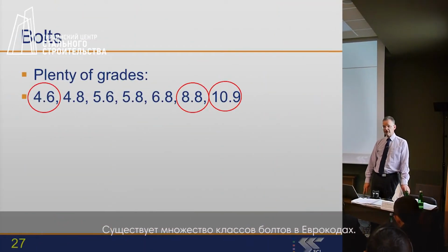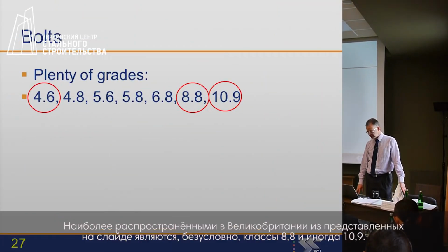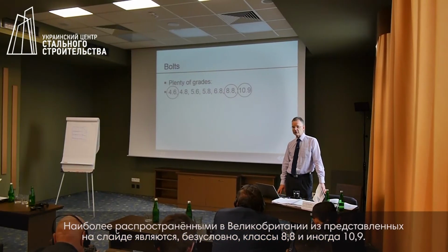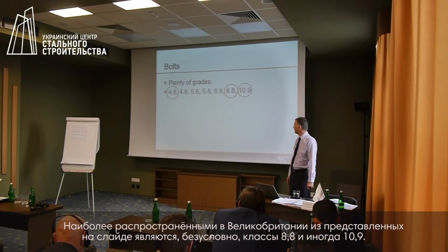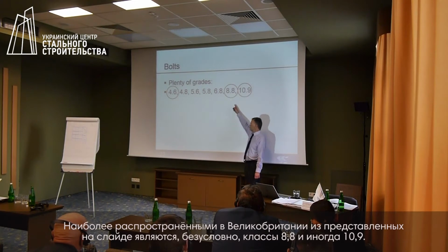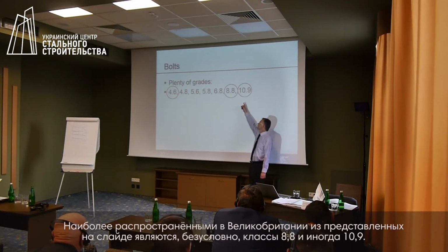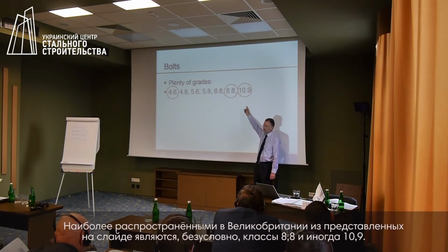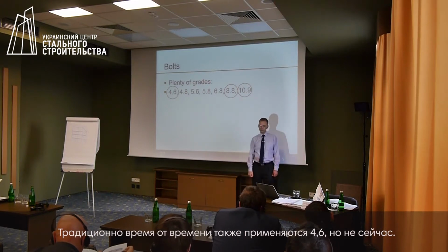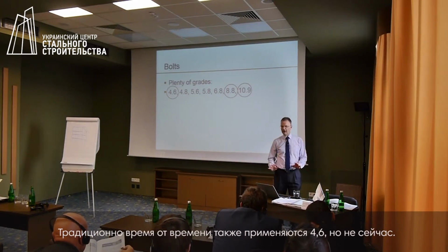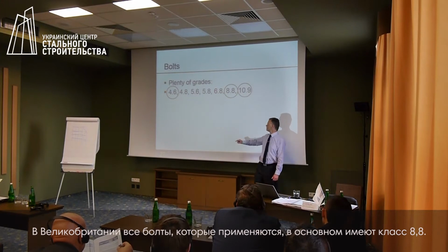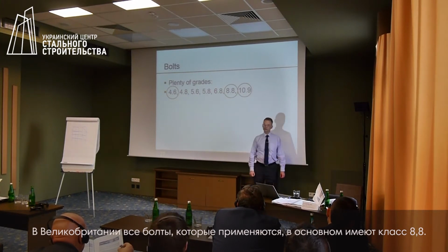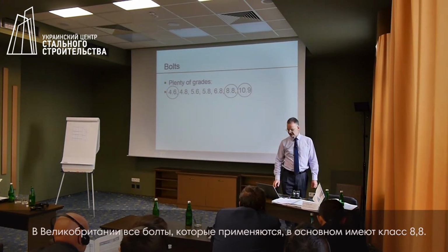There are plenty of grades of bolts in the Eurocode. The grade of bolts that we would find most often in the United Kingdom would certainly be 8.8 and occasionally 10.9. Traditionally we would have used 4.6, but really not now. Almost always the bolt in the UK is class 8.8.